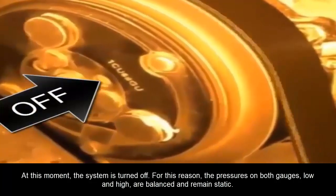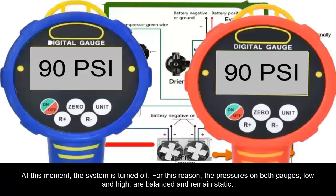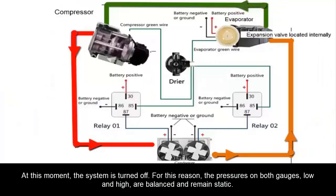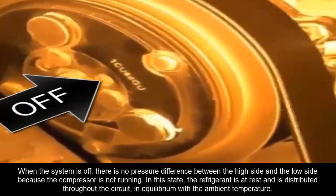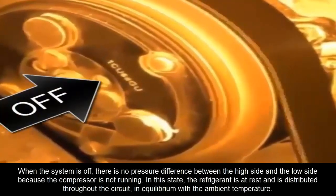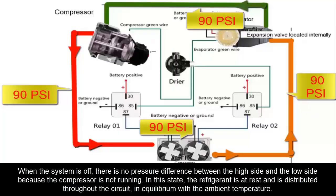At this moment, the system is turned off. For this reason, the pressures on both gauges, low and high, are balanced and remain static. When the system is off, there is no pressure difference between the high side and the low side because the compressor is not running. In this state, the refrigerant is at rest and is distributed throughout the circuit in equilibrium with the ambient temperature.